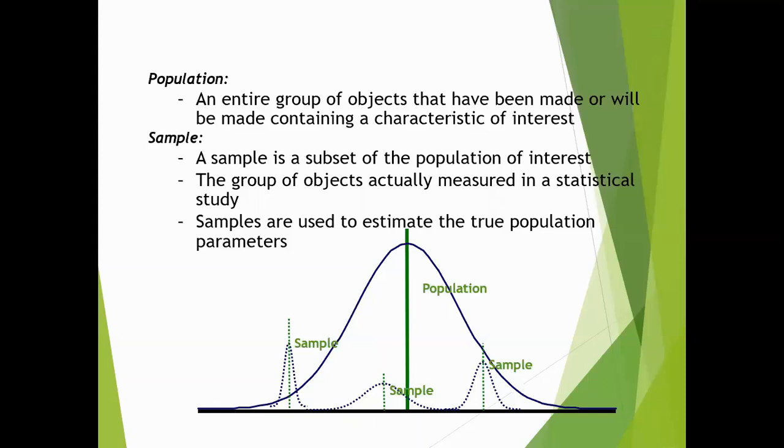So we plot a number of data. We plot either direct population samples, or we calculate the range, or we do a median or mean of the process. We plot it in a control chart. I'm going to show you how that is done. And then we run a test, right? And it will give you two different limits, lower control limit and upper control limit. If all these data points are staying within these control limits, it means that the process is in control.